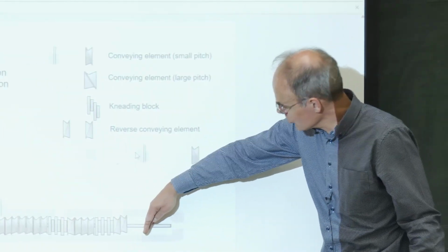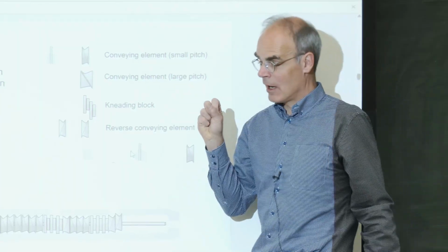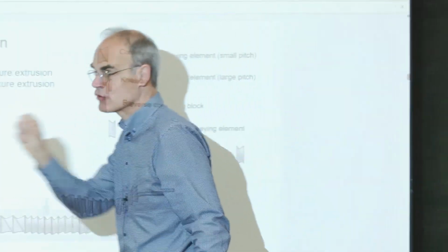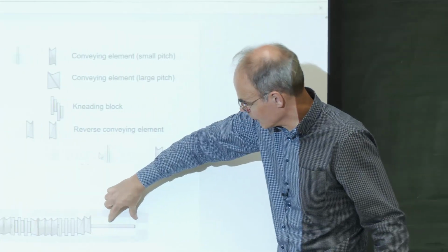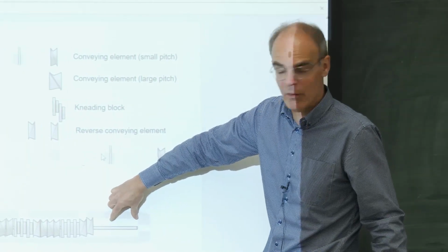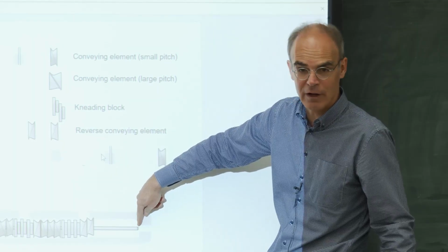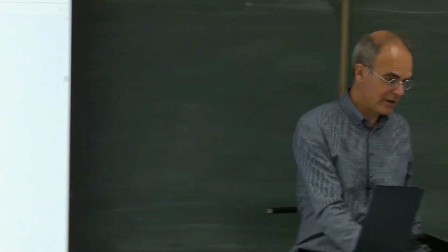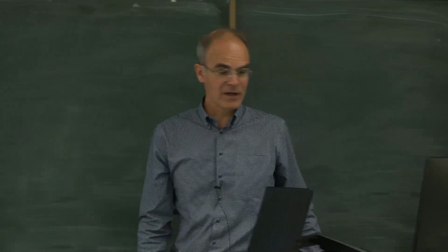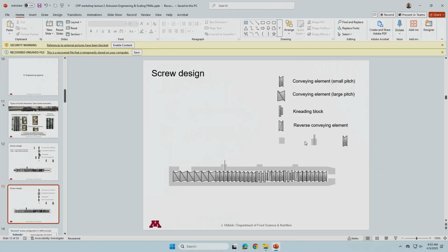You really want to make sure you build up that pressure so that you can actually discharge, that you can extrude that material. So you don't put your kneading blocks right before here, especially not with a reverse mixing element at the side, because it will never get through the die. Good. So if you design a die like that, I think you have a fair chance. This is actually something which I designed here. Of course, you close these ports.